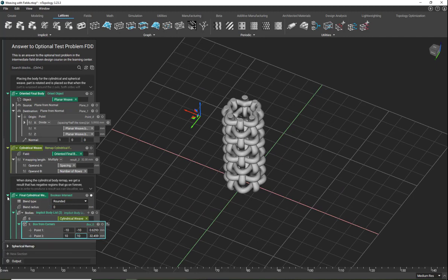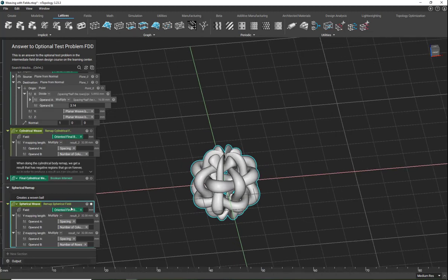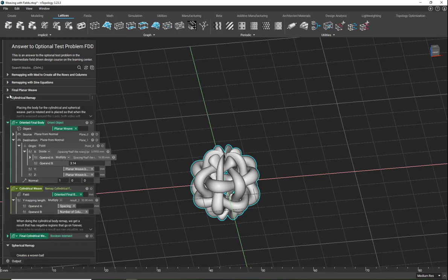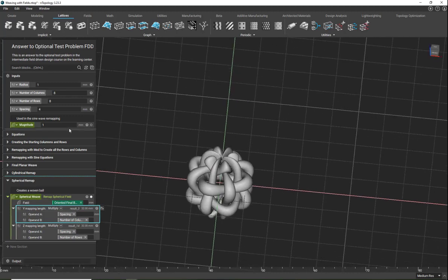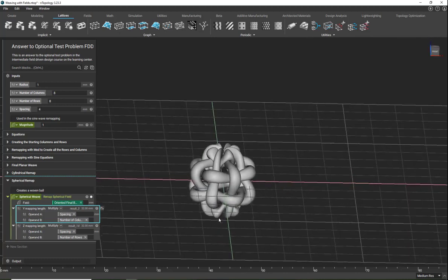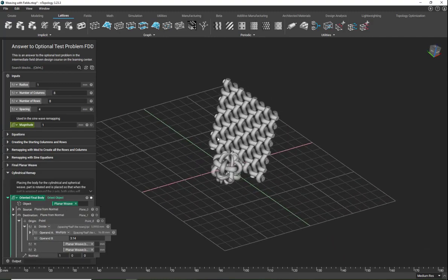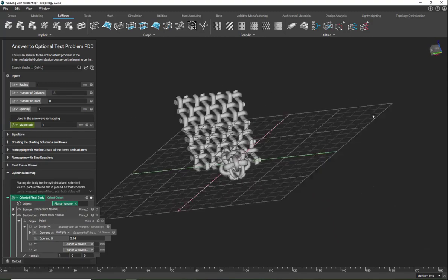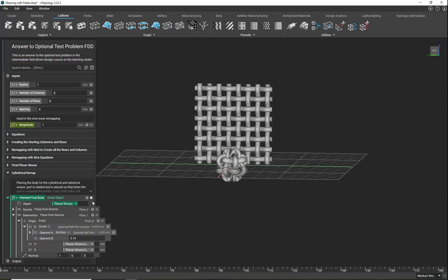And then the last thing we'll do is that spherical remap. And so this is our spherical remap where we have our oriented final body again as our part. We can use that same one we had for the cylindrical remap. Now we have just the spacing times the number of columns and spacing times the number of rows. And note here that while we have 8 rows, we really only have 4 of these. So if we look at that oriented final body again, we're just going to take kind of a portion of that and wrap it around. So we'll just have that 4 going kind of up and down that part, and then 8 of those columns.